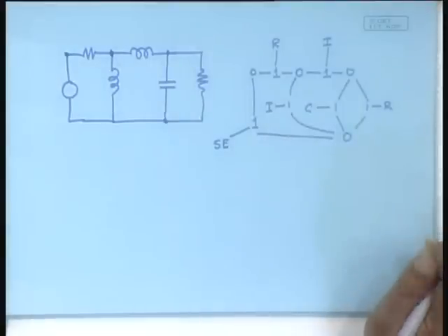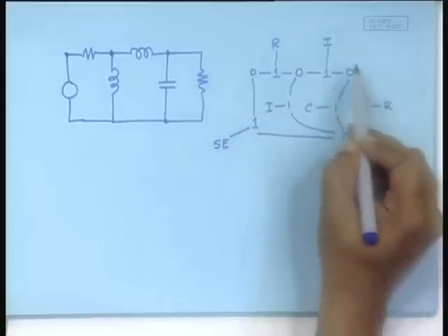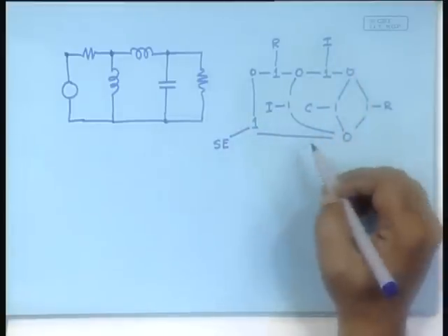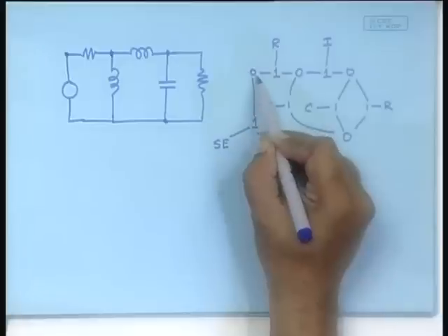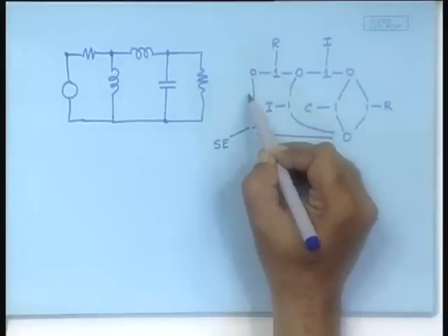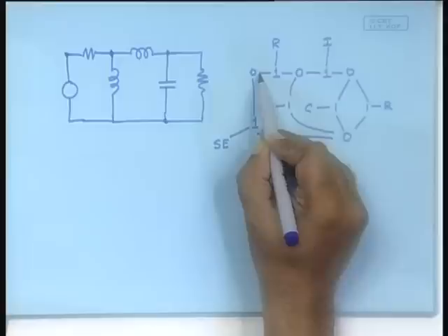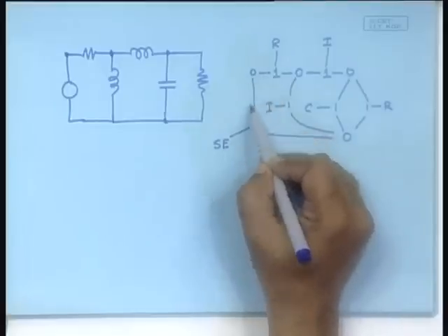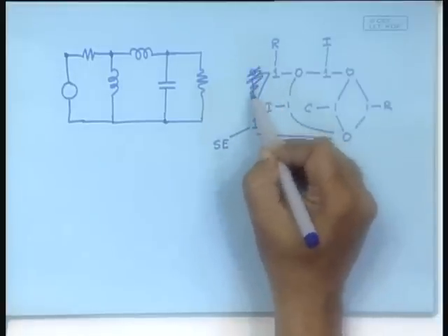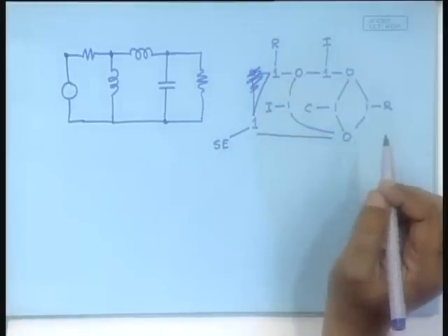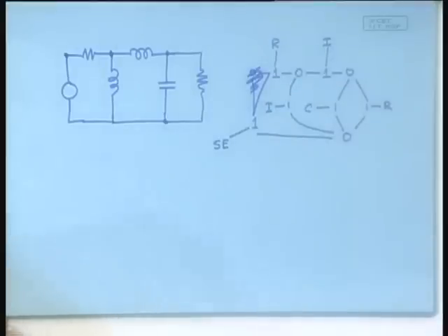Okay. But now we have landed up with a bond graph that will turn out to contain more bonds than you really require. For example, this is a 0 junction which is connected to only 2 things. Therefore, the effort whatever comes here must go here, whatever flow here must go here. The powers are equal and the effort and flow are also equal. Therefore, this 0 junction serves no purpose. You can short it. That is one way of shortening the bond graph.